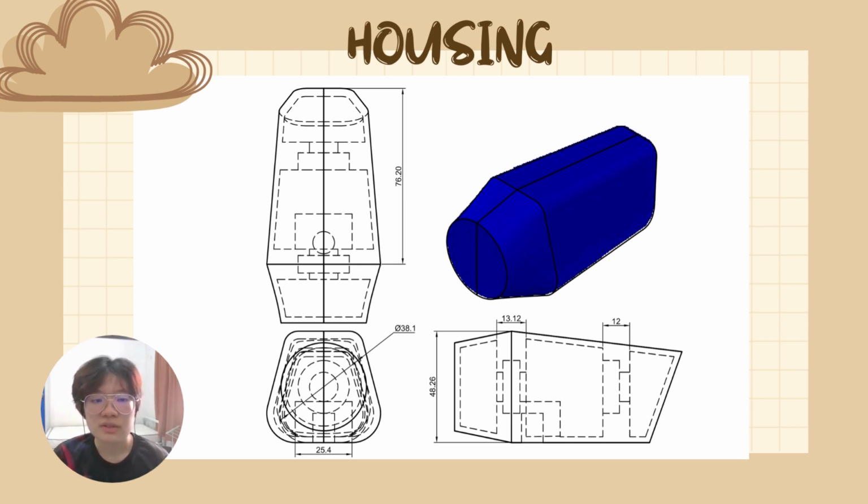Then, two more sets of reference lines were drawn, one between the top flat and the circle, and the other one near the bottom flat surface. The inner housing was built applying both reference lines, and the press pull command was used along the shell's wall. We then used the line tools to draw the wire cover, and we built a screw-like structure in the middle of the shell by applying the loft command to all the circles.